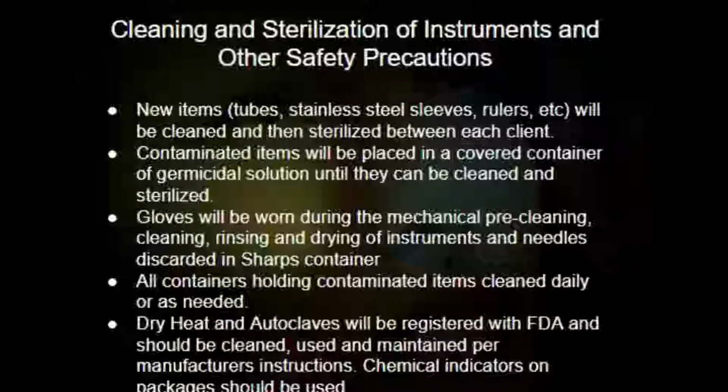The above temperatures relate to the time of exposure after attainment of the specific temperature and do not include heat up or lag time. These time-temperature relationships are recommended, or other time-temperature relationships recommended by the manufacturer of the instrument. For moist heat, or the autoclave, 15 minutes at 121 degrees Celsius, that's 250 degrees Fahrenheit, at 15 psi, which means pounds per square inch. The above exposure time relates only to the time the material is at temperature and does not include a penetration or heat up lag time.